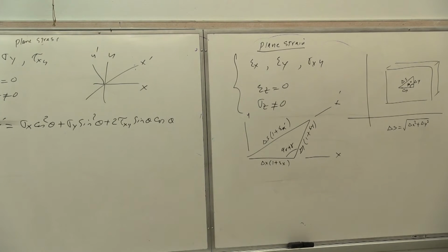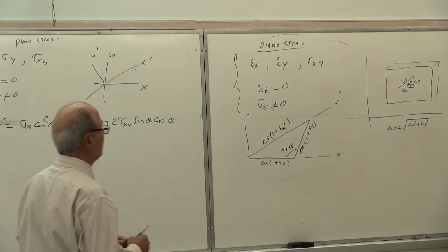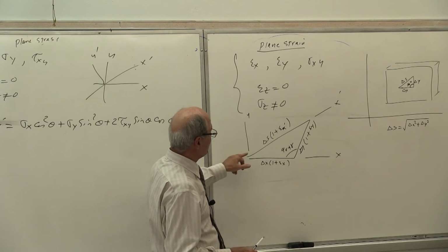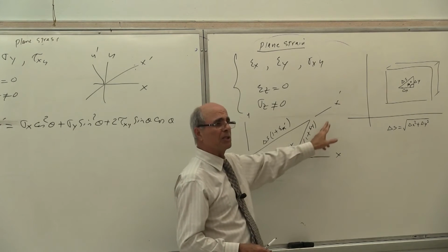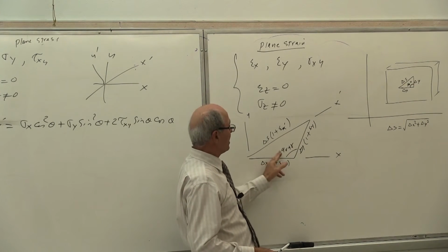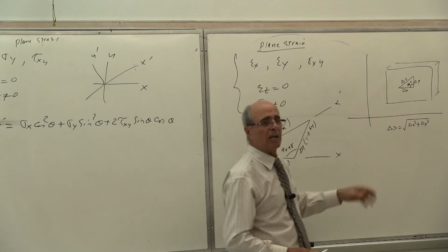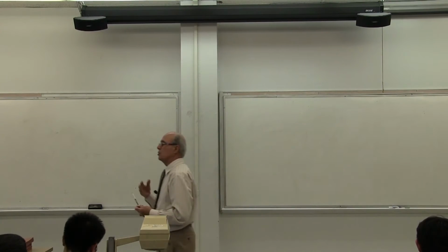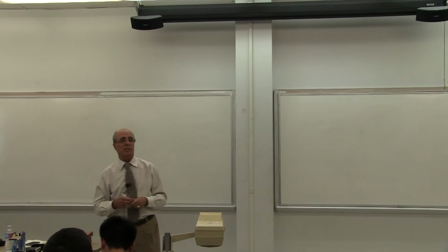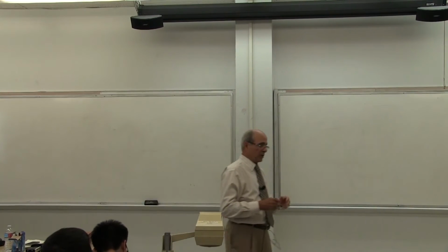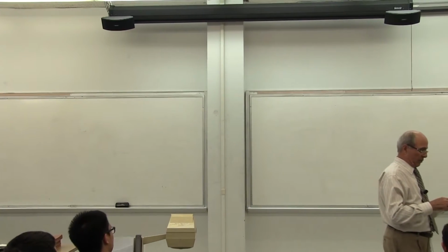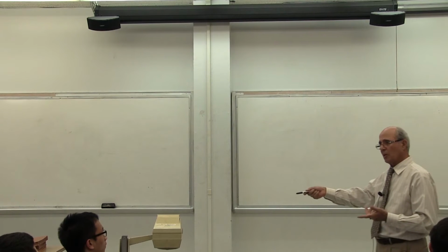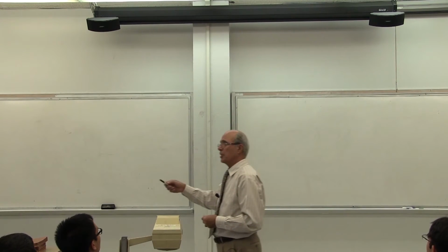Now, after we do that, this is the proof of the equation. You don't have to go any further because the rest of it is really lengthy math. Then we write this. It says c squared equals a squared plus b squared minus 2ab cosine c. We eliminate lots of terms, all the epsilon to the power of 2 and 3. And eventually, we come up with this equation. The goal is to calculate epsilon x prime. When we calculate all of this based on this scenario, epsilon x prime, which is the epsilon in the x prime direction, similarly one for the y prime, which was the idea behind the Mohr circle.